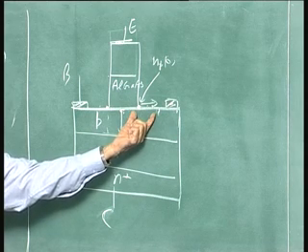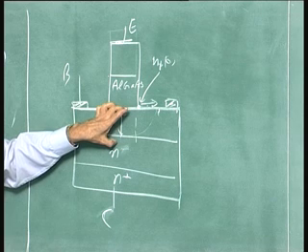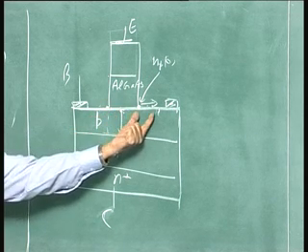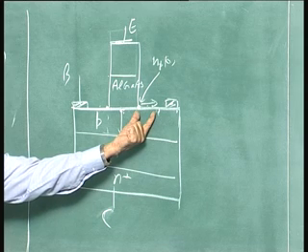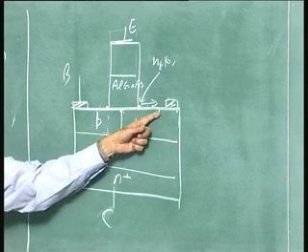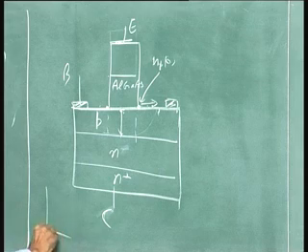So, the area over which the recombination takes place is decided by that width equal to the base width. Now, the carrier concentration over this area is decided by the average value on this. We can take this area multiplied by the average carrier concentration.